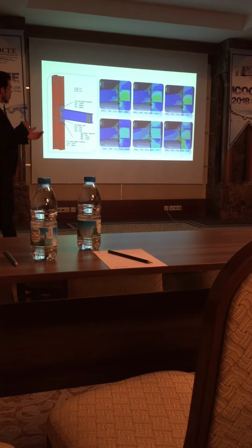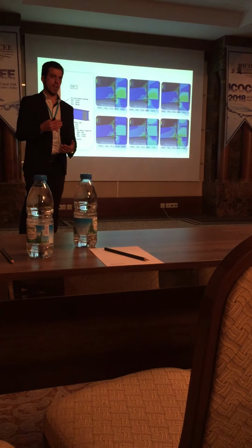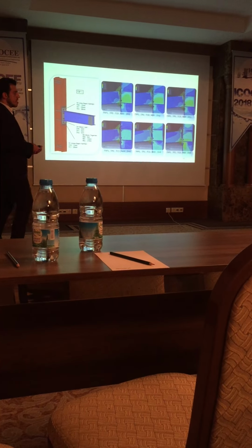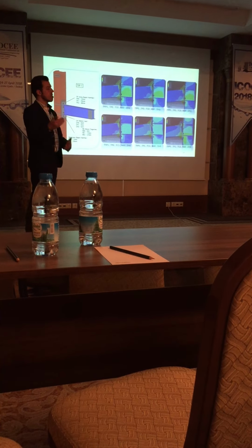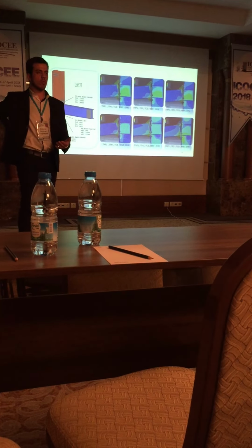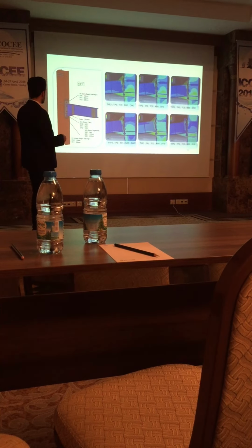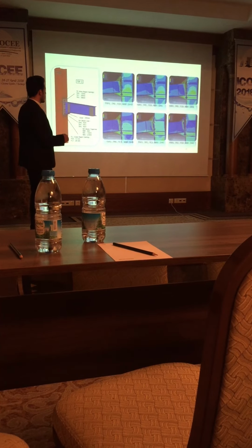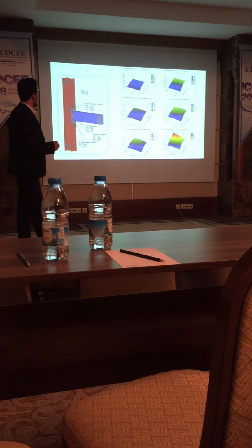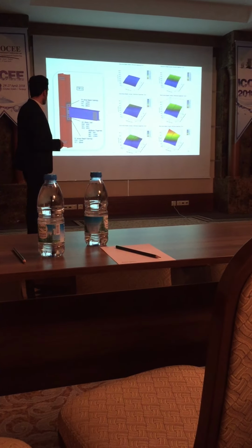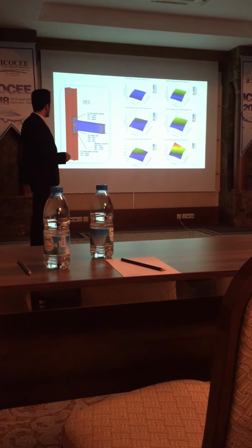What is interesting is that we are doing all of this not by drawing one by one, but in an automatic manner. In Python language we write and then we get the result. If we write this, let's say thickness 20 millimeter, 30 millimeter, it changes across all 270 combinations. And then this one, Gusset, and then this, as you see, it's different. Then we obtained these three-dimensional graphs.